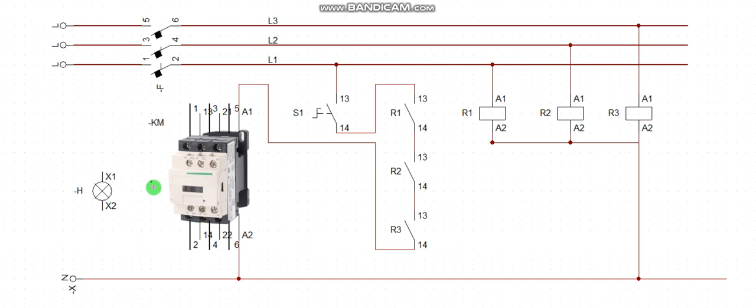So if you're not doing that and you're using direct off and on to energize your contactor, I'll be left with 13 here. I have the 13 terminal. So I use it to take power from here. Then this is the 14. I bring out 14 here. I use that 14 now to feed my lamp. So that is the NO auxiliary contact. Okay. I also energize this with my neutral.